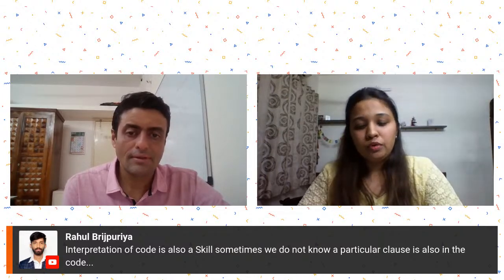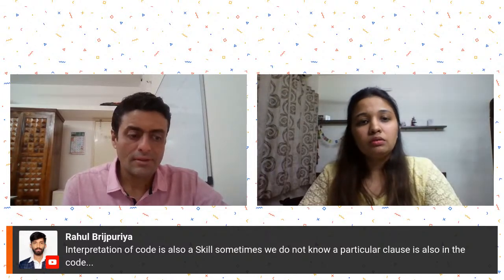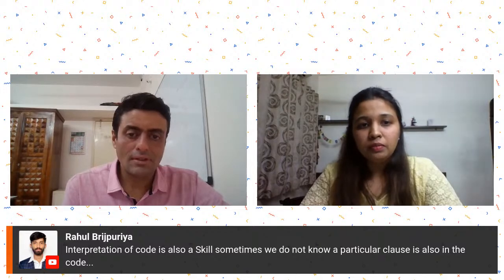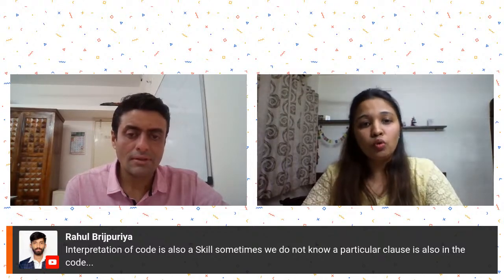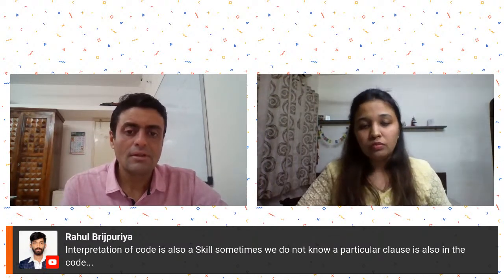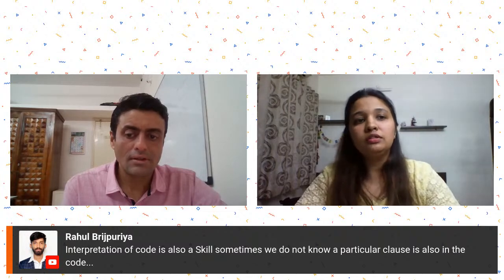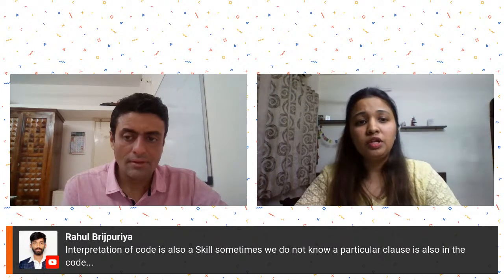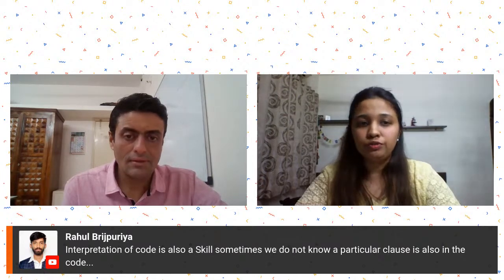For many years, we were designing bridges by WSM. Even in BE, I learned the design of bridges by WSM method only. Then later the LSM code came into picture. So they have published one explanatory, in which they have given interpretations and solved examples. The explanatory is IRC SP 105.